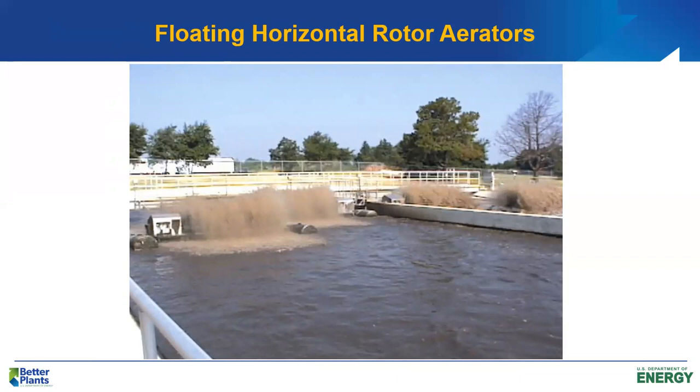They can be used to replace fixed rotor aerators that have failed. And the nice thing about the floating horizontal rotor aerators, they can be placed in the ditch in a few hours of time without actually taking the ditch out of service.